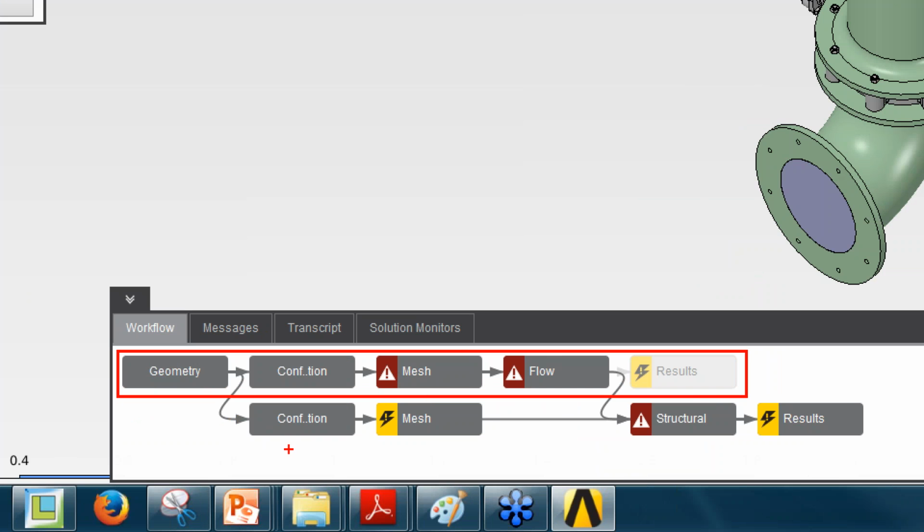But then I also want configuration of the internal part. I have a reed sensor inside, and my goal here is, if I change the valve angle inside, I would like to know the stresses as well as the streamlines, the pathlines, etc. for the fluid flow. What about the velocity vectors? I'm interested in both the fluid simulation as well as the structural simulation. So you see that little icon right here, that tells me how it automatically couples, or it allows flow of information from the fluid flow analysis to your structural analysis. Okay.